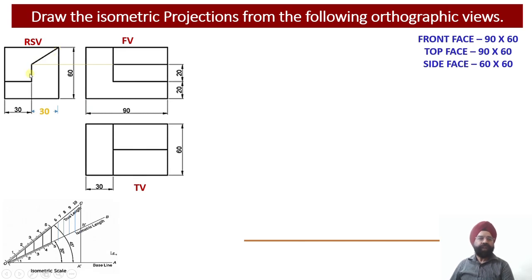Okay, so now the first segment is a flat segment that we will be drawing. Then the second segment is the vertical surface which is visible in the front view. So this is the true shape of this surface which we are able to see. And the dimensions of this surface, total length is 90. The length of this surface is 30. You can check this one. So the remaining surface length is 60 millimeter over here. So this surface will be 60 millimeter long, right? So with this we can see over here. This is 60 millimeter long.